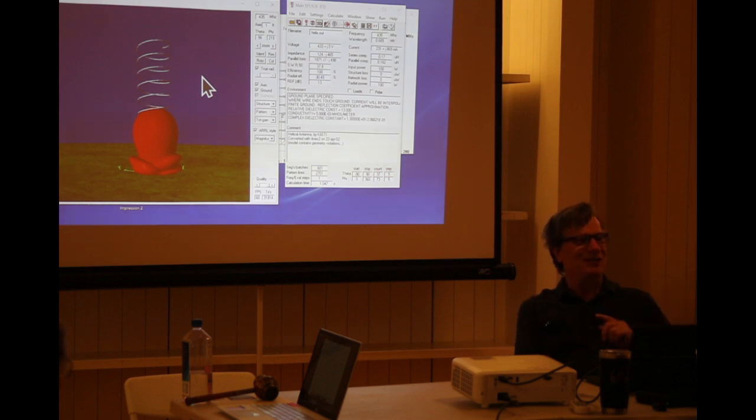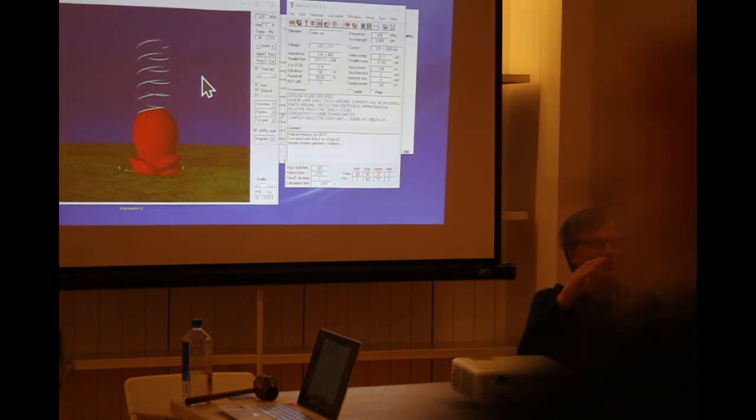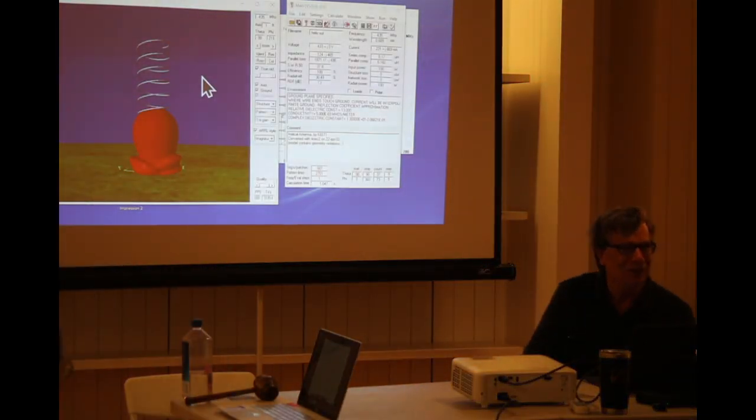Now, how do you prevent that? A tapered feed. You don't feed it uniformly. Your feed horn adjusts it so you don't have anything going toward the edge. So it makes sense. But you sacrifice gain. Everything's a compromised antenna.